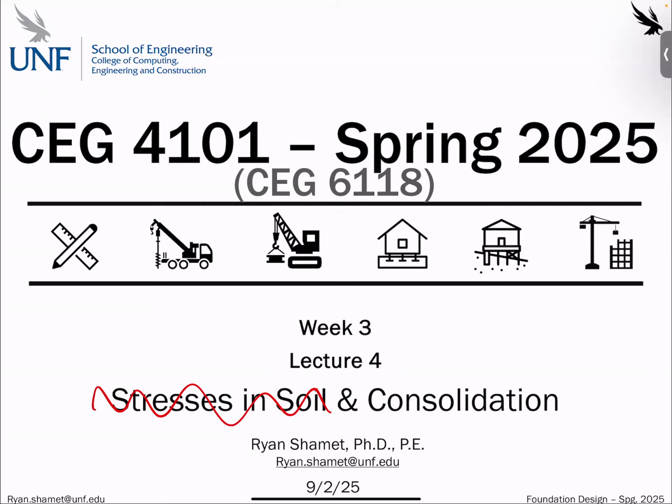Clay. Yeah. So if we're drilling down and it's just 200 feet of sand beneath us, we don't have to worry about consolidation at all. We don't have to do any of those testing. If we have layers of clay or organic or silt or anything that has a low permeability coefficient, then that's when we can get into the consideration of consolidation.